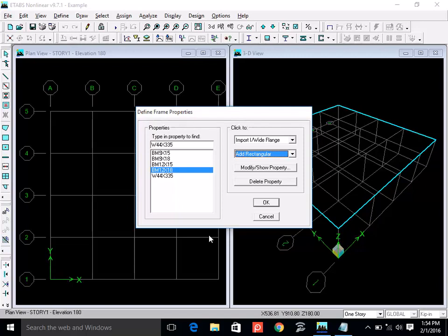So remember, as a general rule, that minimum size or minimum dimension of column which is practically used is 12 inches. 15-inch is a desirable size, or it's a good size. So generally our sizes, when it is square, start from 12 inch by 12 inch, 15 by 15, 18 by 18, 21 by 21 in multiple of 3 inches.